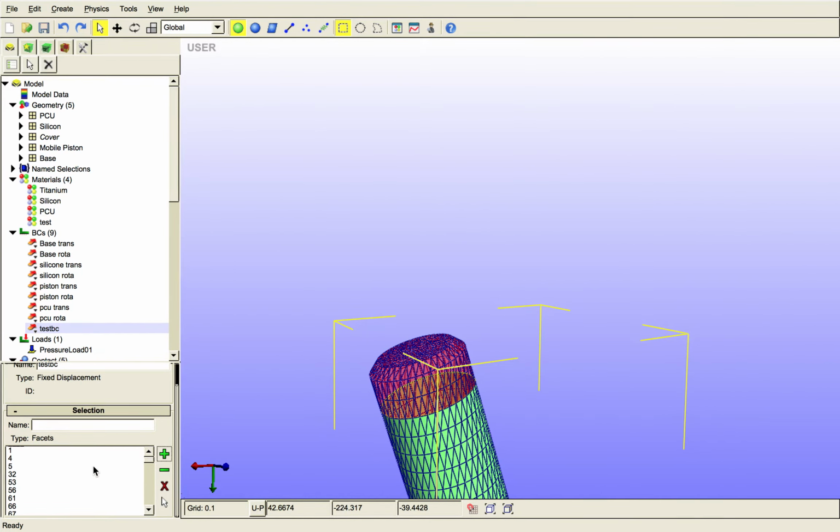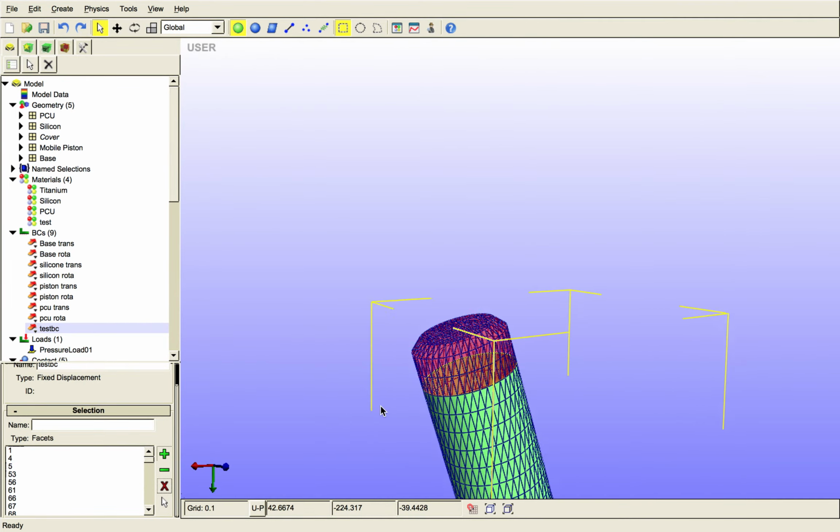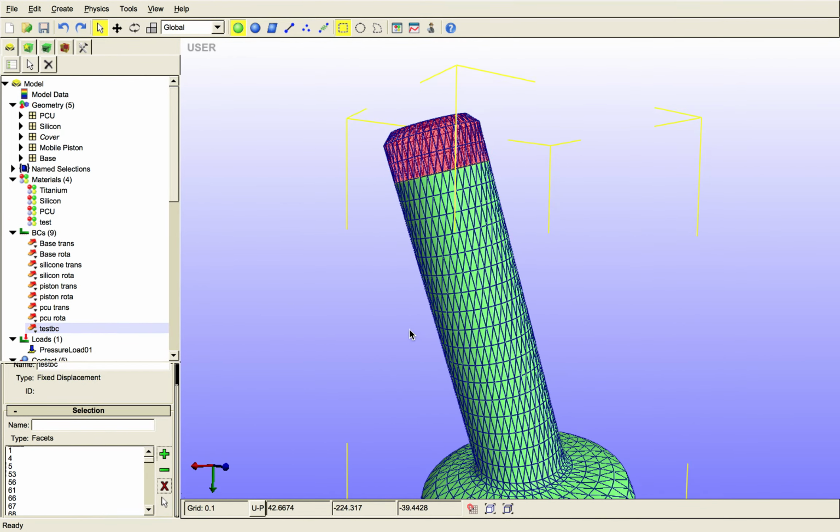If you want to remove one of them, just click and, this is the thing that you mustn't do. If you want to remove only one of them, you have to use the X button. If you use the minus button, it can sometimes, I don't know why, take everything off, so you have to be careful about this. So I'm going to add them again and just select one of them, and there you go. This is pretty much everything.